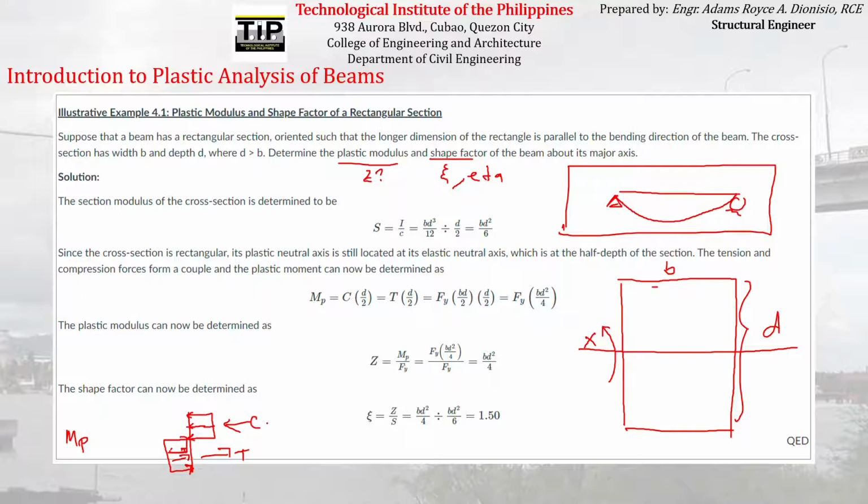Okay? So with that, we can relate the plastic modulus and the section modulus. Especially kapag kukunin na natin yung shape factor. So that's the first thing that we have to compute, yung section modulus nito. And section modulus is just equal to moment of inertia divided by c.